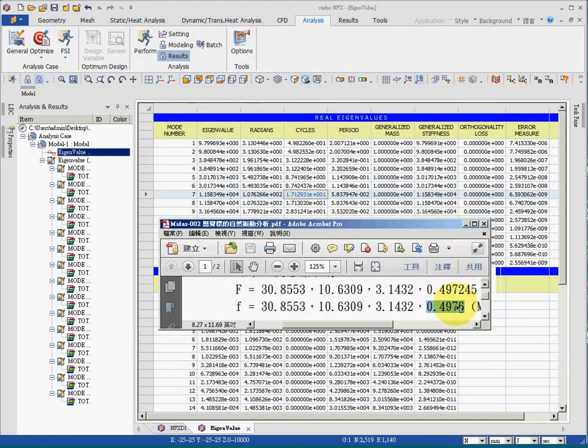The reason is that in solid mechanics or mechanics of materials, we calculate the cantilever beam with a neutral axis. It is a one-dimensional simulation of the three-dimensional geometry. But in modal analysis in CAE, we use 3D models instead of only one line.